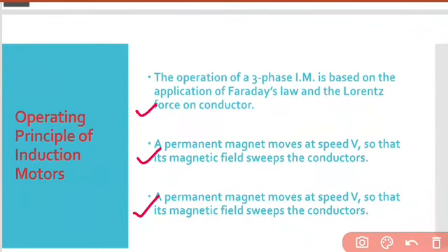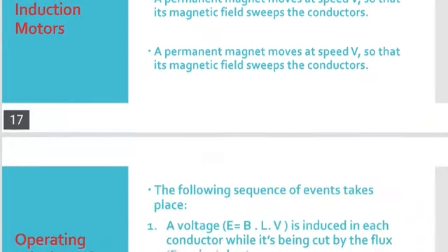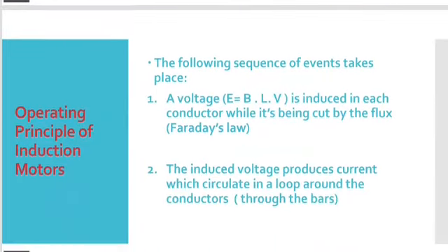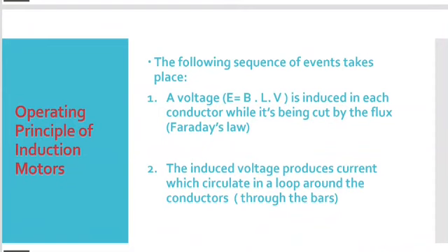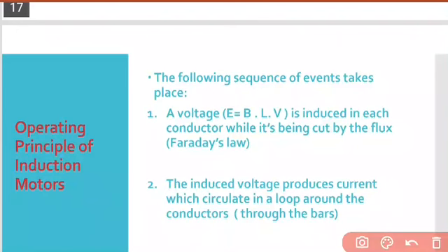Okay, next, these are the steps which we are going to consider in the operating principle of the induction motor. The first step is that a voltage E = BLV is induced in each conductor while it is being cut by the flux. That is Faraday's law.